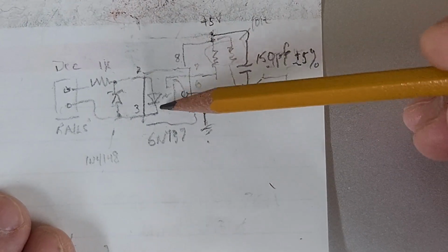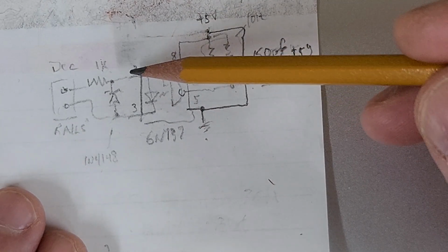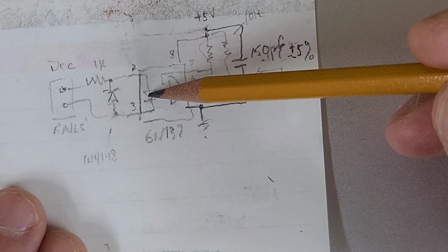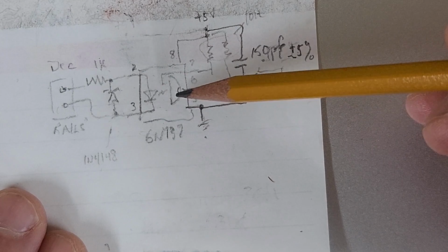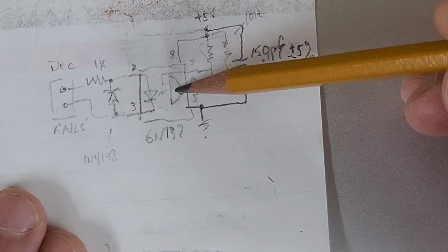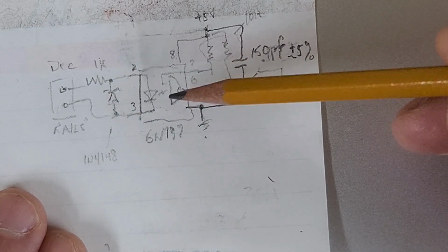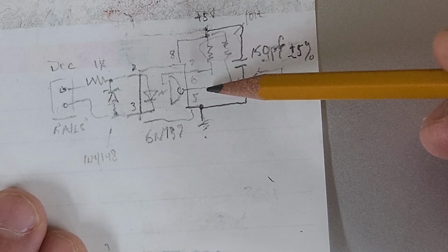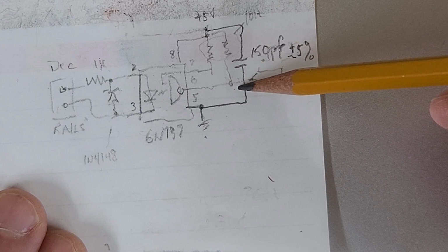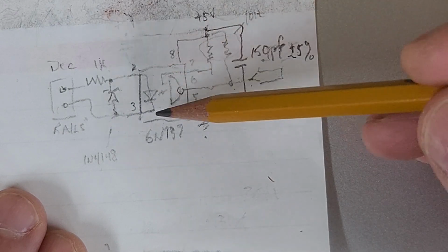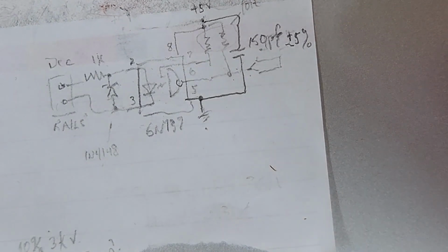The signal, once applied to the input of the optocoupler, is going to cause, every time you see a positive half cycle where there's current flowing, a light generated from that LED within the optocoupler. And then this light-sensitive AND gate, well, actually it's a NAND gate, every time it sees the light pulse, it turns on its output. By doing that conversion, on this side of the optocoupler it's 5 volts. So the 5 volts is a good input for the Arduino.